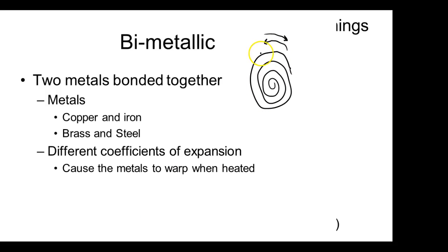And then, of course, they've got a switch mounted right here. So when that thing coils or uncoils, when we set a temperature, the switch is basically going to be at a level, and it's either going to tilt one way and set one set of switches, or tilt the other way, depending on if we have the thing set for cooling or heat.